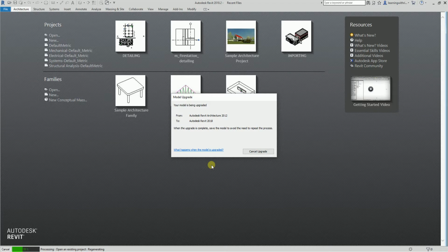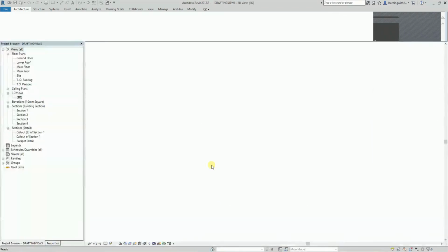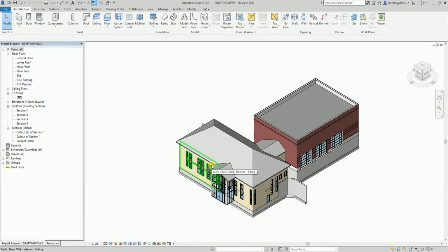And another thing, any callouts placed in a drafting view must be reference callouts, because as you can see, a drafting view is actually just a 2D drawing. So you need to reference any callout that you're going to place on your drafting view. Okay, so what else? Although not associated with the model, you can still drag the drafting views from the browser into the drawing sheet. Okay, so you can do that.